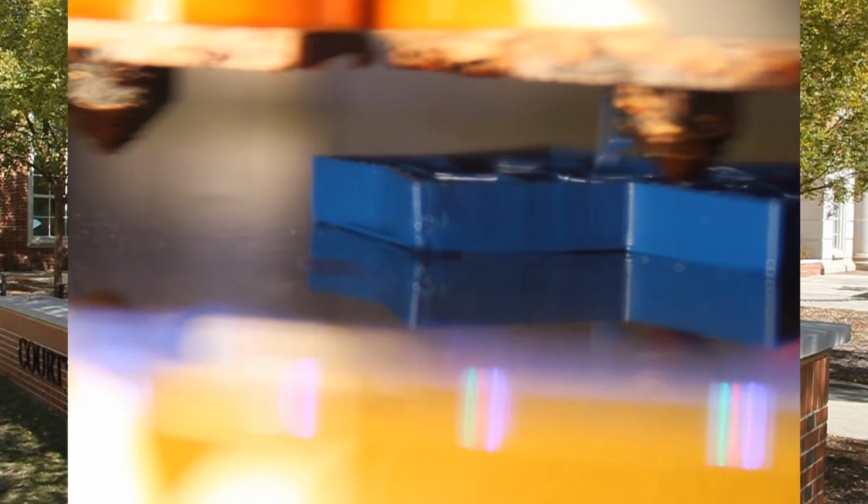So just tell me, what are some of the problems we have with 3D printers? The one that we're looking at is warping, which is when the corner of a part starts raising off the platform before it's even finished printing. Other ones that we've seen are problems with resolution. Depending on how dense of a product you're trying to make, there can be gaps in the product that make it so it's not the ideal flush, flat surface.